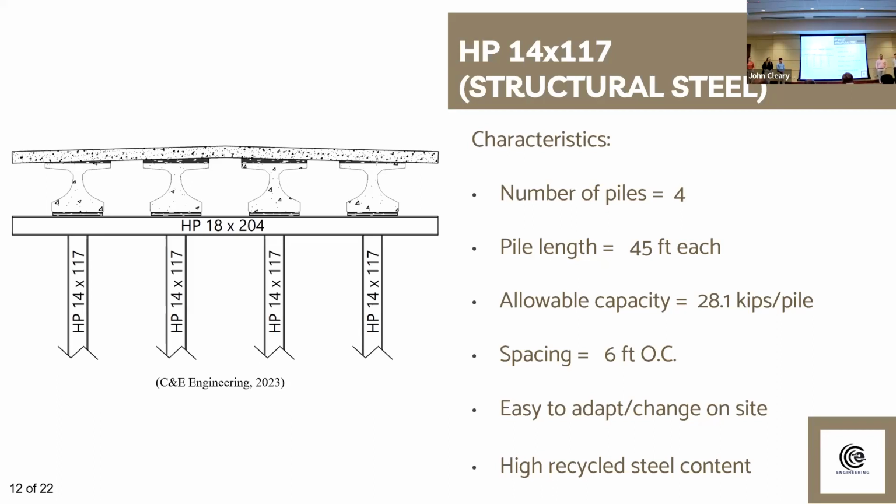How are you going to retain the embankment materials behind the bridge approach? How will you retain the embankment materials at the abutment? Behind the abutment, we'll have sheet pile walls, and in front of the abutments, we'll have riprap to help protect against any erosion. And the riprap in areas that need it will be rock fill.